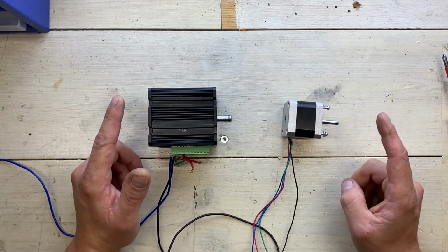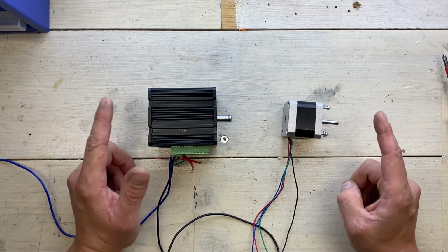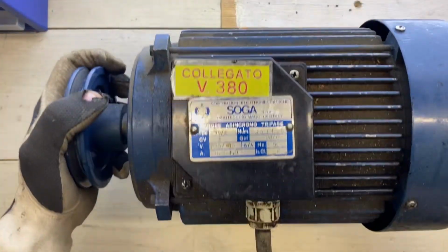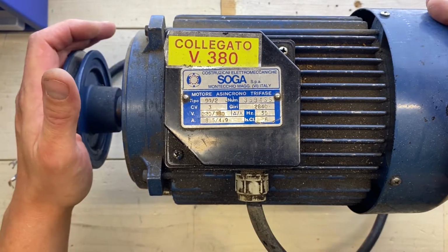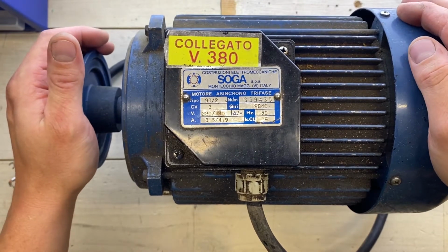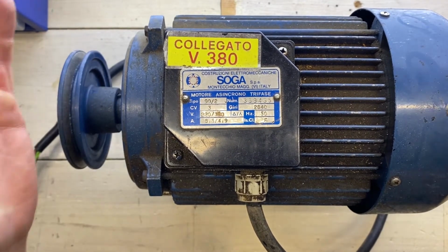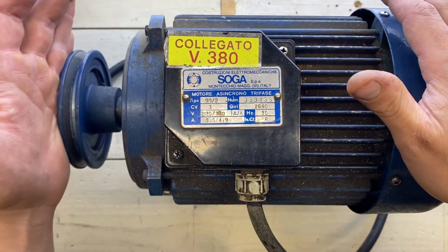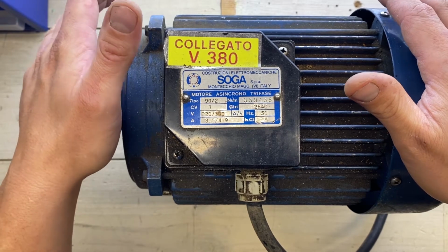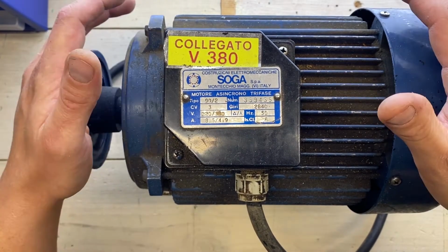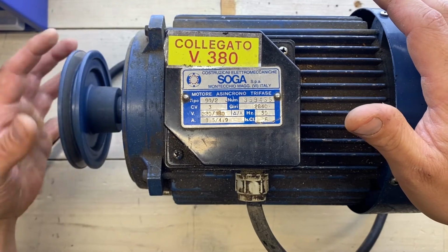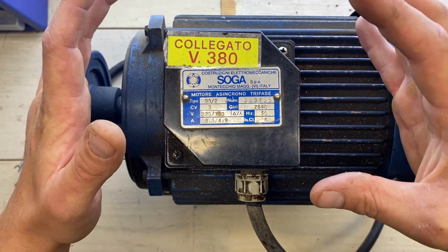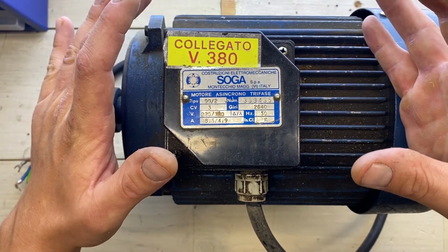Now I'm going to show you the last motor for the day, and that is a 3-phase asynchronous AC motor. This is a 2 kilowatt 3-phase motor out of a compressor. And this is a whole other animal than the other motors I've showed you. It doesn't contain any brushes, as the stepper motor or brushless DC motor, but it doesn't have any permanent magnets inside of it either. The 3-phase power induces a current in the rotor, the current drives a voltage, and the voltage creates a magnetic field. And to explain this a bit better, I'm going to draw some graphs.